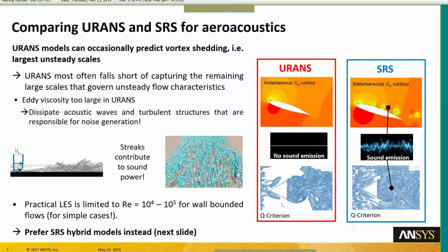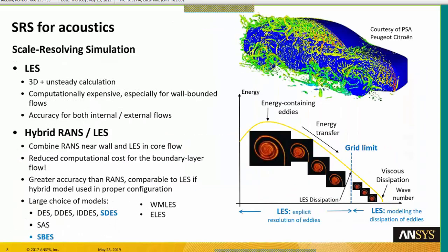But we were talking about LES for hybrid RANS-LES models. Usually it's better and easier. Why? Because with this combination of RANS and LES, we resolve the motion of large eddies far from the walls, since near the walls we would create small eddies, and that is quite expensive for LES.